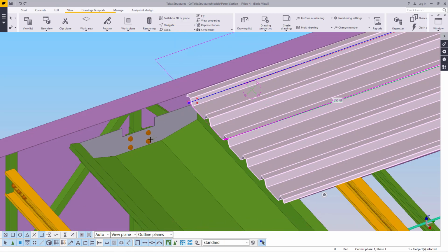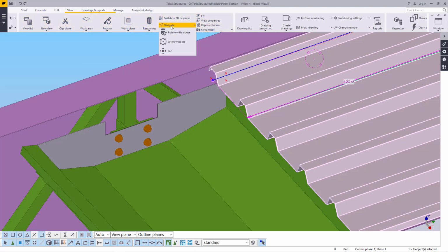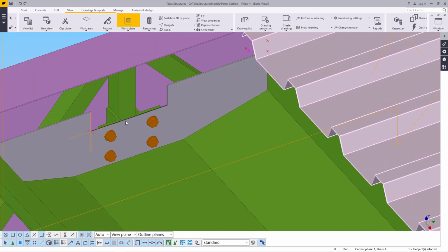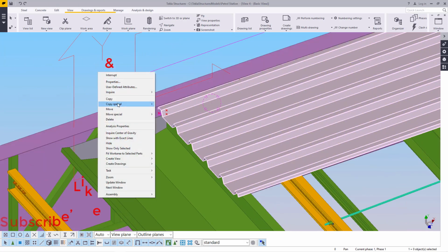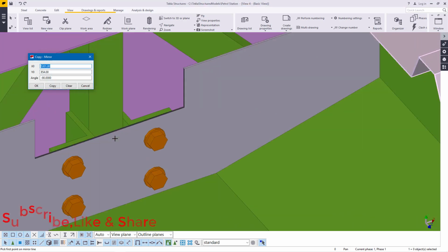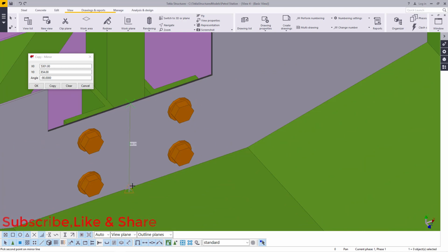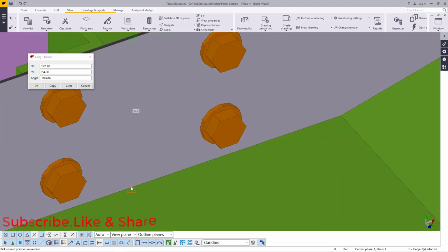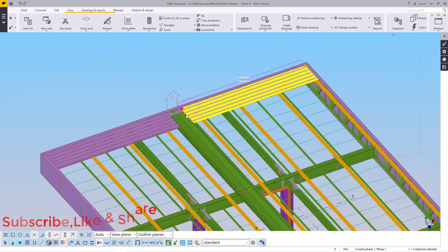Now once you've done that, we want to reorient again our XYZ plane. You come to work plane tool here and pick it under work plane, and we'll place our XYZ axis. Then we'll come to mirror. Then we want to mirror this. We'll use this point as our mirror line. We'll snap on that spot and straight all the way to the bottom end here. Make sure you snap on the straight line right there and click OK, copy. So we have it here.